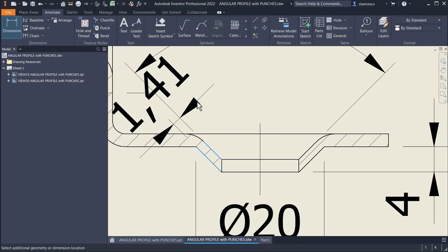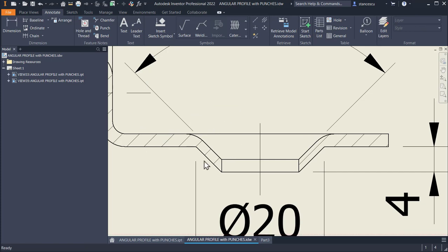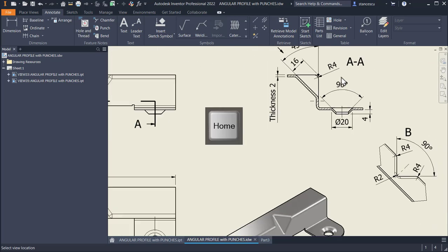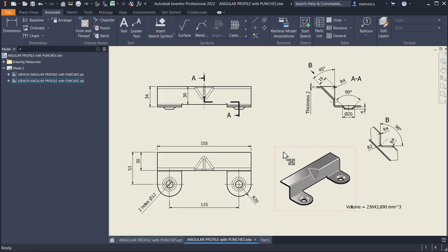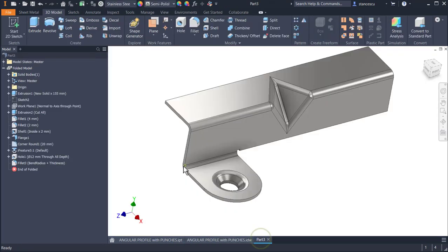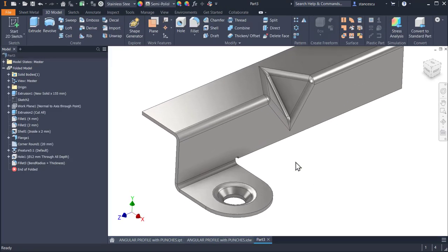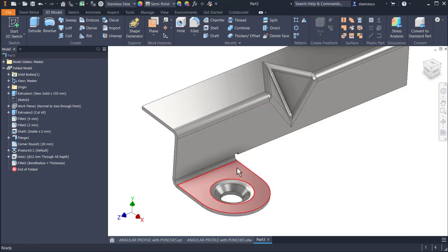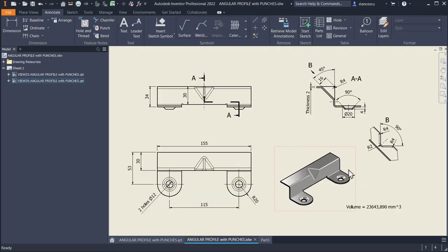This is not good. If I apply our routine of revolving here, and you can see it in my previous tutorials about sheet metal parts, then I control everything. This is a motive for me to not use this tool, punch. And another motive is this one. Look here. Now I want to mirror, yes, to mirror all these features from the flange to the bottom, to have another replica or another feature, identical one, about the midplane.